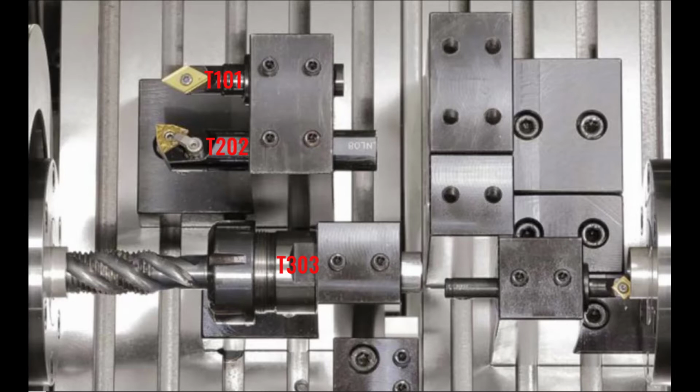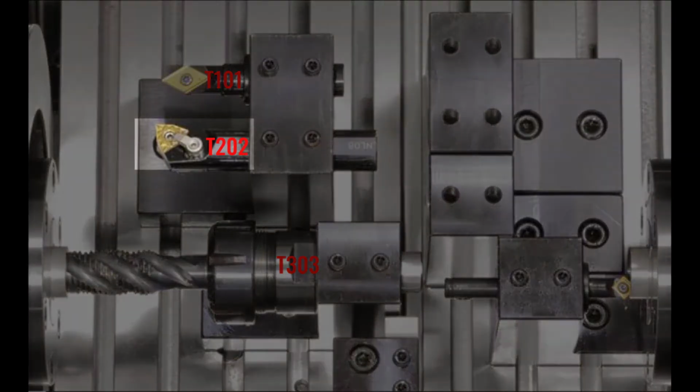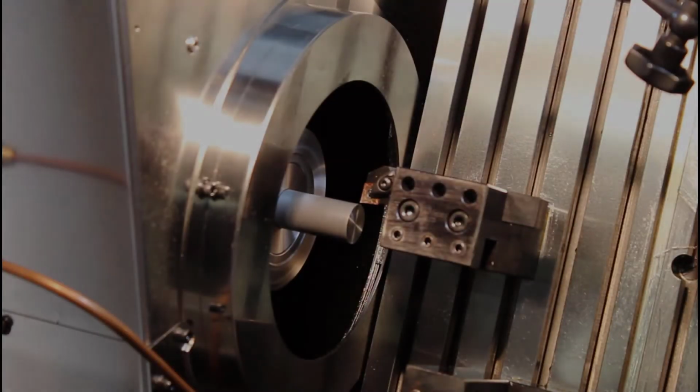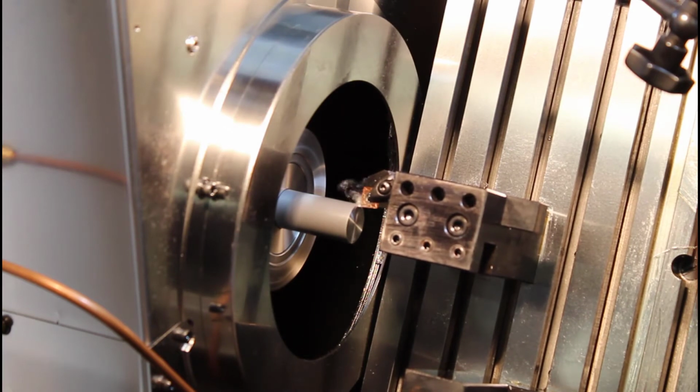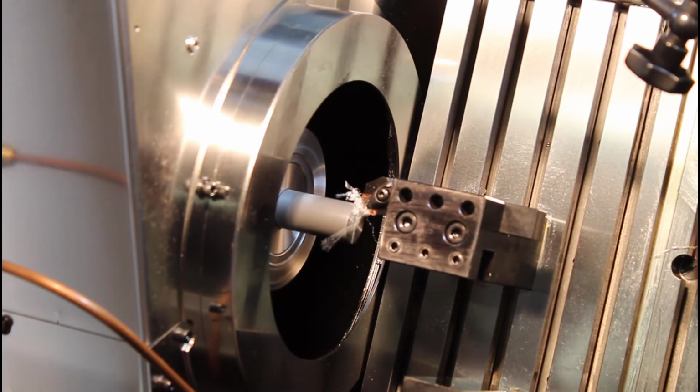The gang style tooling allows you to run right and left hand tools with the insert up or down. In some cases, you may be working on the negative side of X. Pay close attention to the orientation of the tool and the side of the work you are machining. Using the hand wheel, take a clean cut on the face of the material.